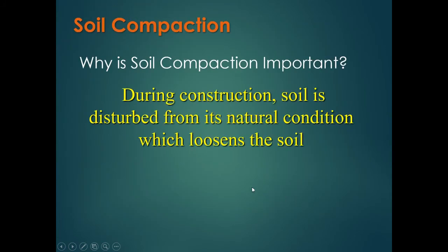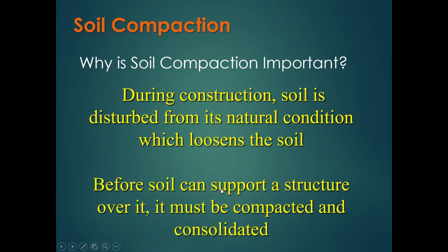Okay, why is it important? During construction, soil is disturbed. Even though we're digging in a foundation in natural soil, there is still some disturbance there. So we want to make sure we compact it back into place. Before a soil can support a structure over it, it must be compacted and consolidated.